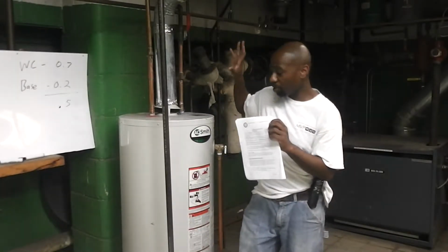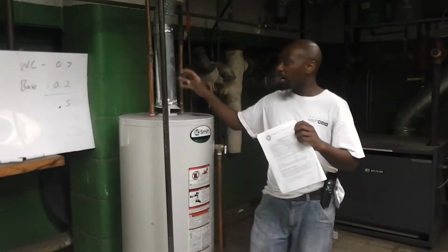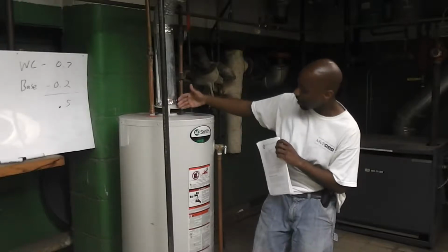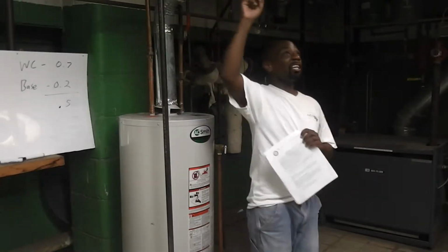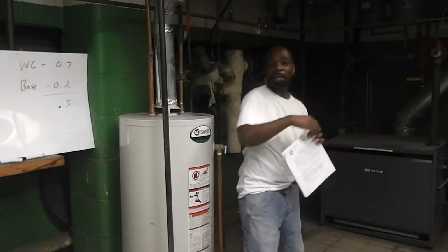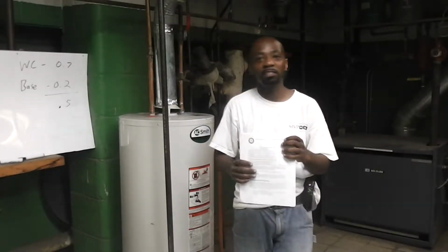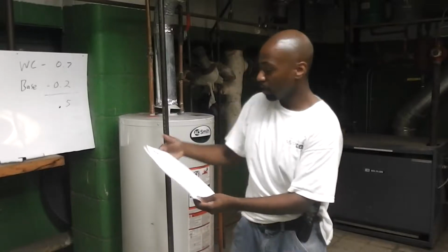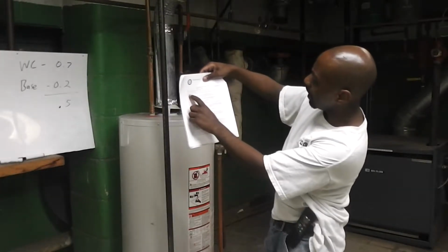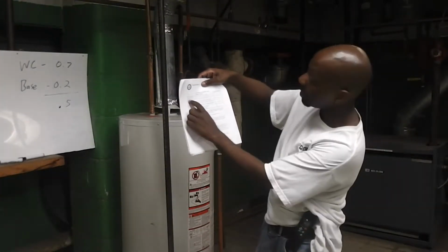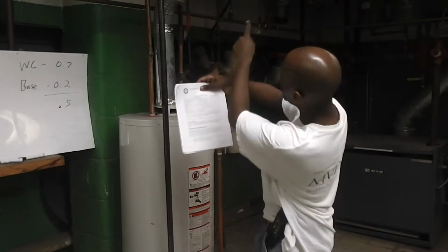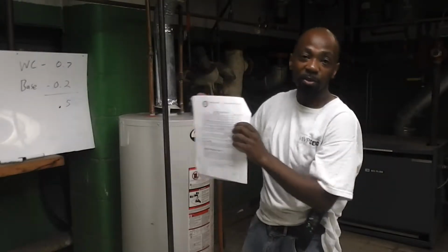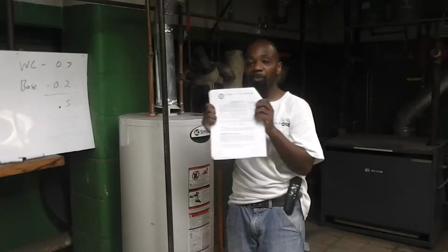To figure this out, I need to look around and figure out what kind of condition I'm in. I see a combustion appliance here, my DHW. I see that it's atmospherically vented, check out how it's open. And the flue pipe is connecting to another combustion appliance, which is also atmospherically vented. So there are two commonly vented combustion appliances in this CAS. I'm looking at line number 2, natural draft boiler or furnace commonly vented with a water heater. So our limit is -3 pascals.